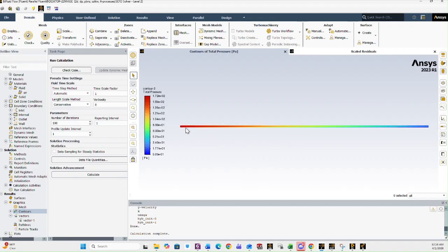total pressure changes from the beginning all the way to the end because of the initial velocity. It will decrease as it gets towards the end. There's going to be a negative pressure gradient pushing through here. So there's going to be less pressure here, more pressure here due to that static plus dynamic, where the dynamic is less here, but the static stays the same.